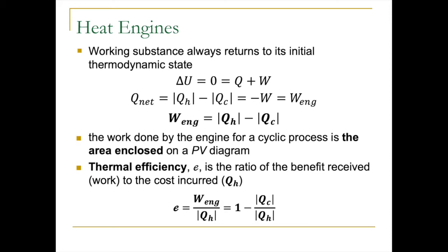The other quantity that's going to be highly useful when discussing engines is thermal efficiency, which is basically telling us how good our engine is at converting the input heat into mechanical work, or whatever kind of work we want done by the engine itself. You'll notice that if we substitute in the equation for the work done by the engine, you can simplify this equation into 1 minus Q cold over Q hot. Notice again the absolute value signs so that we don't have a sign mishap when we actually do the mathematics.